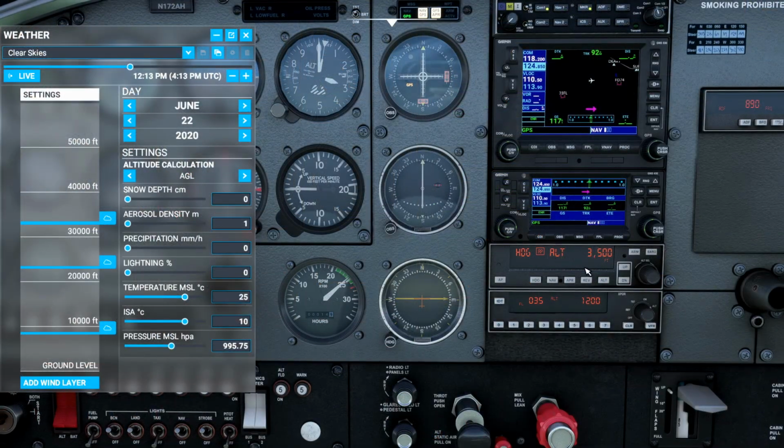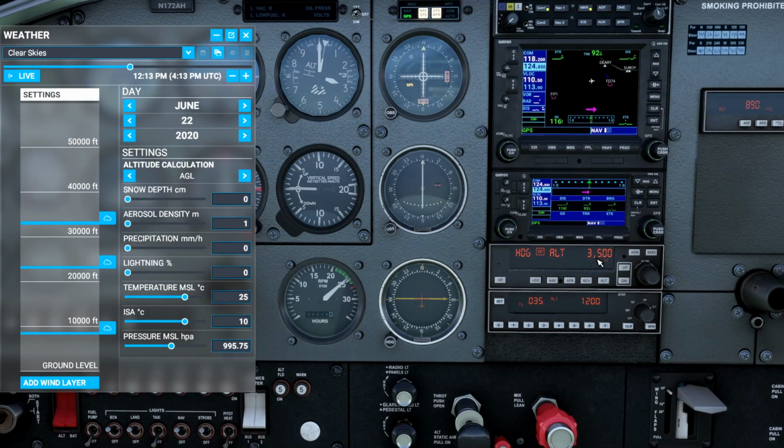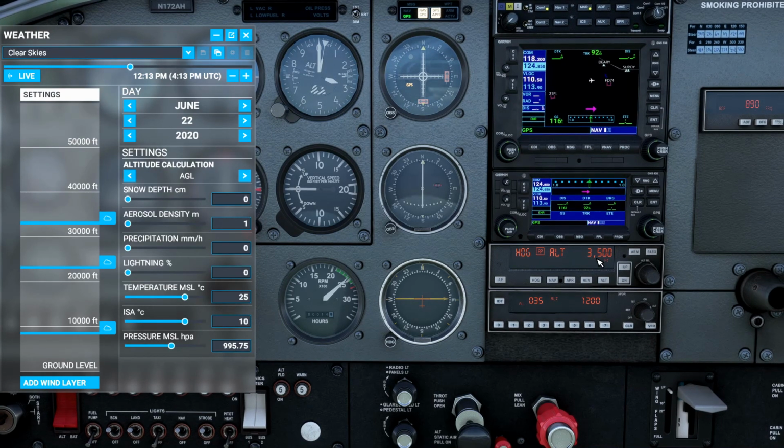One other little note about the altitude pre-select mode is that I said earlier in the video that this BARO function does not work very well. Well, really it doesn't work at all, and that causes some problems with capturing altitudes if your altimeter setting is not standard, if it's not 29.92. It'll be minimal if it's not very far off, but if you get up to 0.5 inches off on the altimeter setting, that's an altitude error of up to 500 feet, and a little bit greater if pressure goes above or below 0.5 from standard.